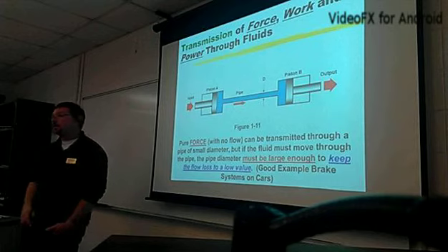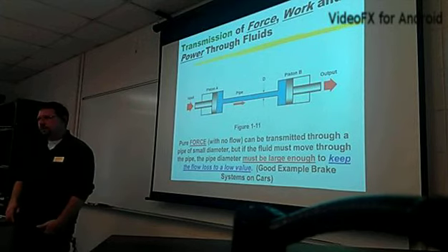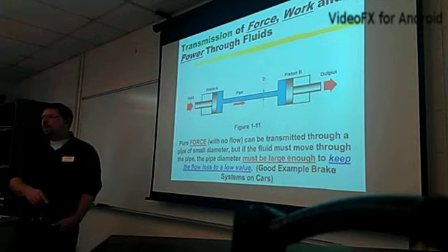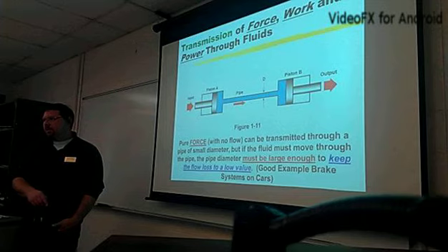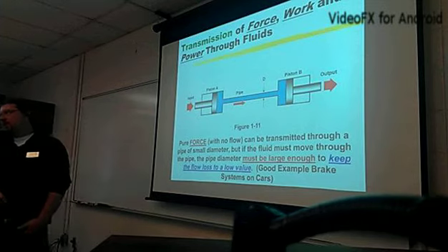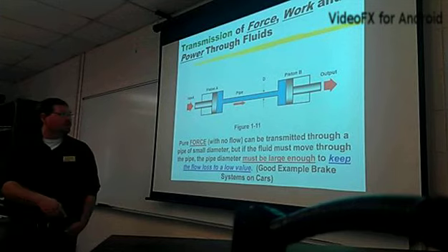more so than air systems. When they're reduced in that manner instead of that venturi the way you showed it, you get more friction because it's not a smooth transition from one pipe to another. Well, yeah, you can. We get into the deal about elbows and turbulence and stuff later on, but how you run your pipes also factors into your flow, into your pipe loss over distance.